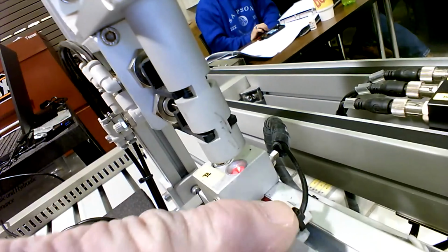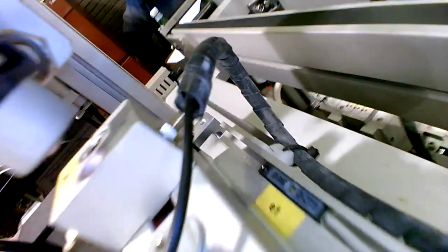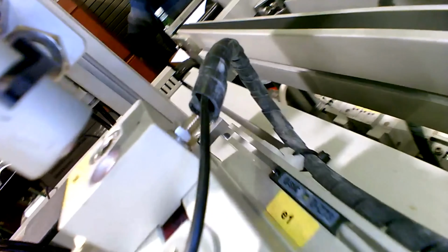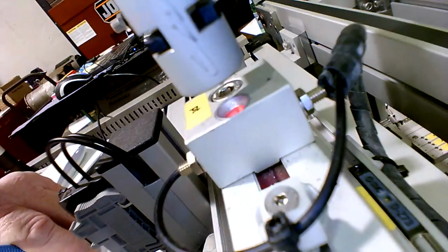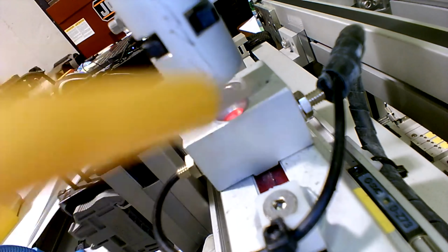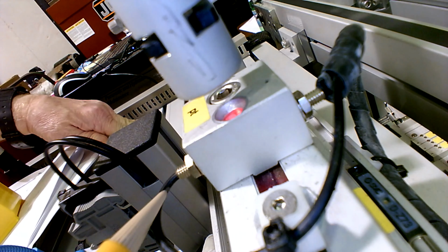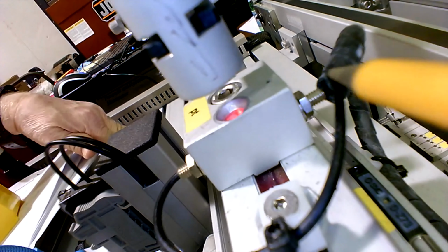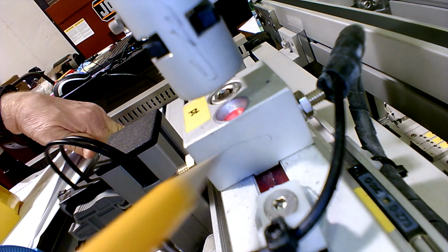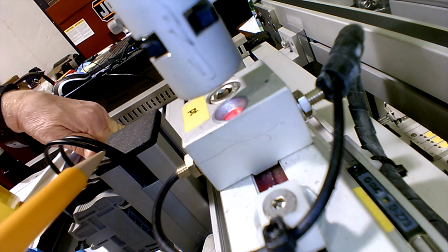You see in here, you got a fiber optic line that goes into here, into that block where that red light is. On the other side, you have another fiber optic line. So look closely here. Watch close here. On this side, you've got a fiber optic line shooting into that block through a hole. It shines through a hole in the block. The other fiber optic line takes the signal back. So this is actually fiber optic carrying a light beam. There's a light beam that shoots in one end of it over here through the block, and you see that red glowing light down in that hole, and it comes through here, and the other fiber optic line picks up the light signal.